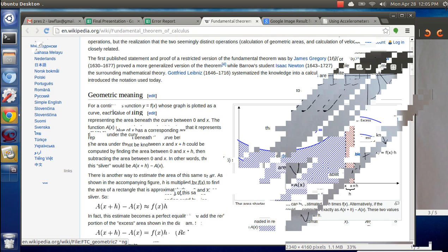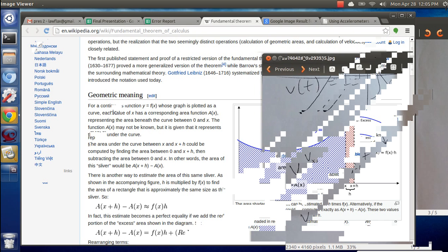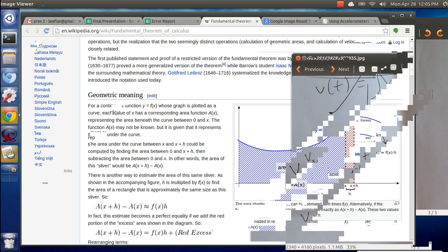So what we want to do is to get the summation of all these rectangles. For our first calculation, for my purposes, we had to start from rest, so we can assume that this initial velocity is 0. And what we're going to do is add the acceleration that we're reading at that moment times our time frame. You can think of this delta t as the width of these rectangles.